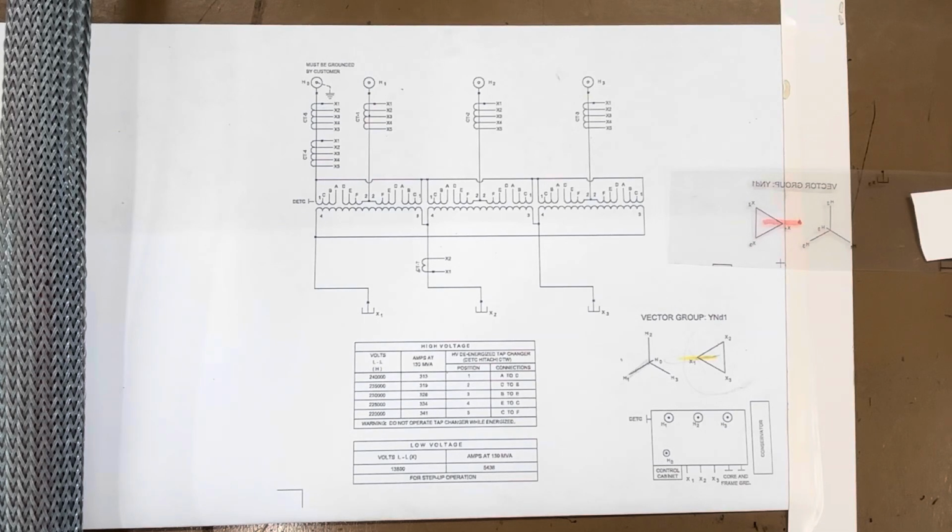So why this is important is that if you had two identical transformers wired up where one transformer saw ABC phase sequence and the other had ACB, and you tried to parallel the secondaries, there would be a 60-degree discrepancy between all three phases on the secondary, and that wouldn't work out so well. So we're going to go ahead and move into showing the setup.